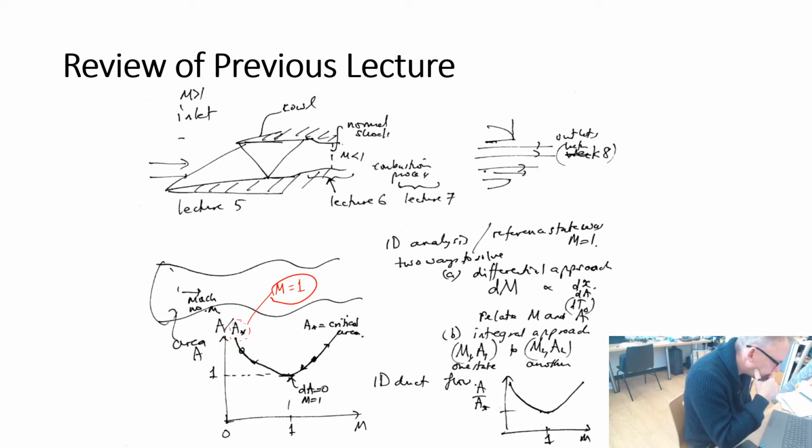when flow is adiabatic, no heat is being added, and the flow does no work. Stagnation pressure is not a conserved quantity. The ratio of stagnation pressure to stagnation density is a conserved quantity, but the stagnation pressure and stagnation density are not conserved quantities. And they are useful as an indication of the potential of the flow to do work. So that's why we calculate those, and that's why we need to go for a series of oblique compressions in order that the loss of stagnation pressure is greatly reduced.